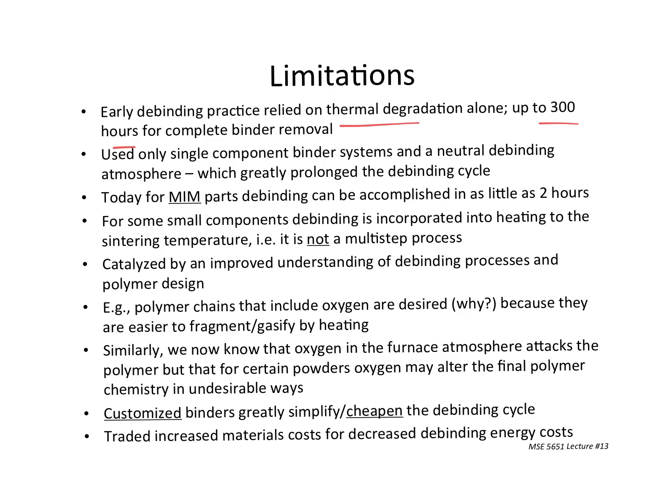In many cases, they used only single component systems and neutral debinding atmospheres, which greatly prolong the debinding cycle. Today, however, we can achieve debinding in as little as 2 hours, and we've talked about some of those processes, the force flow, where you add an additional pressure to it, but we also designed the binder system to make this overall process more efficient.